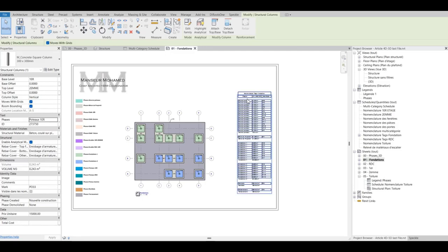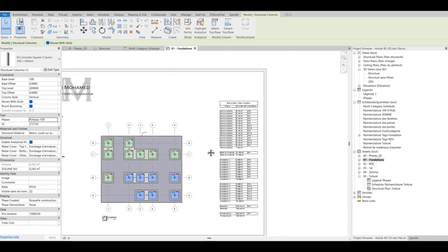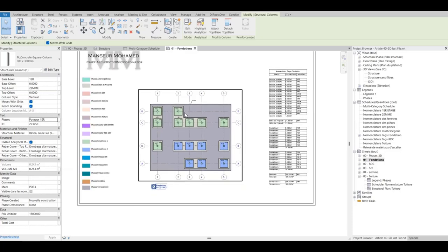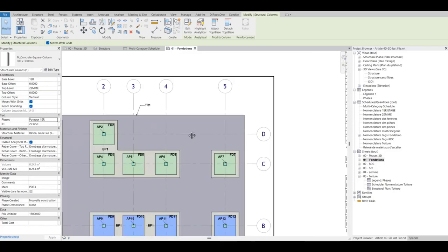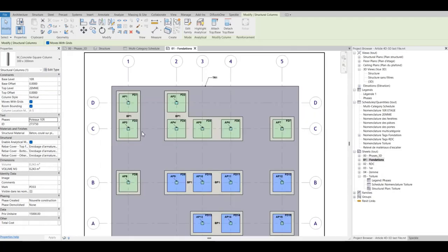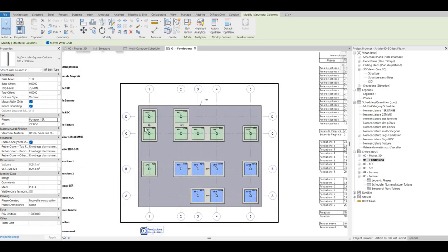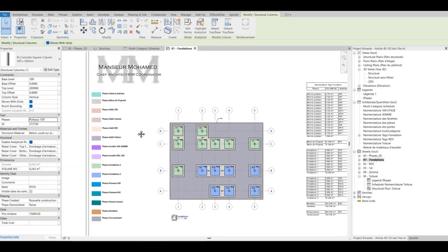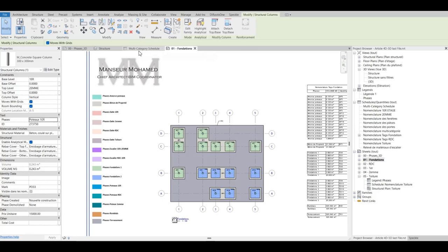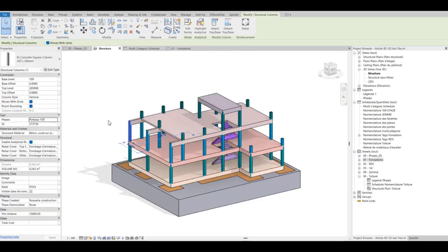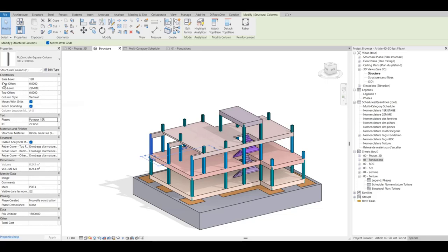Later, we'll demonstrate how to link the ID and geometry using Speckle. Additionally, we will link the tag in the schedule with the Google Sheets to further connect the geometry and the information. We've also created plans for each floor, allowing us to track every element in 2D using tags, following the traditional system of tracking elements on site.